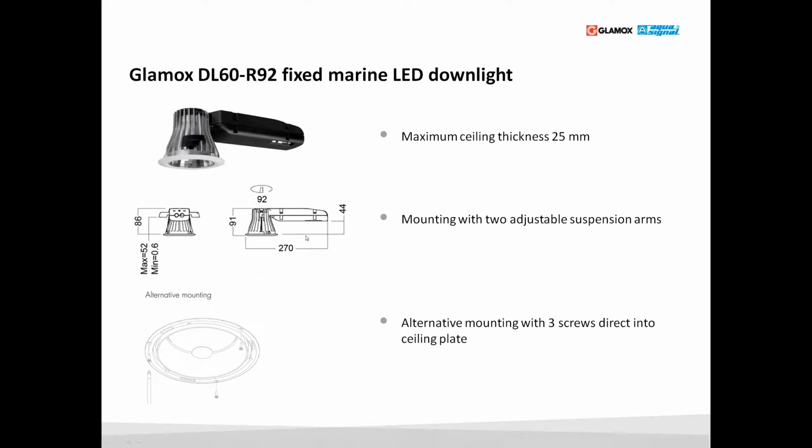But that's not possible. When you are putting it up through this hole, you need to tilt it a little bit up, then you have a lack of distance. So when you have maximum 25 millimeters, then you are able to get it up in the ceiling. If you have less, it's even better, but 25 millimeters is a limitation.